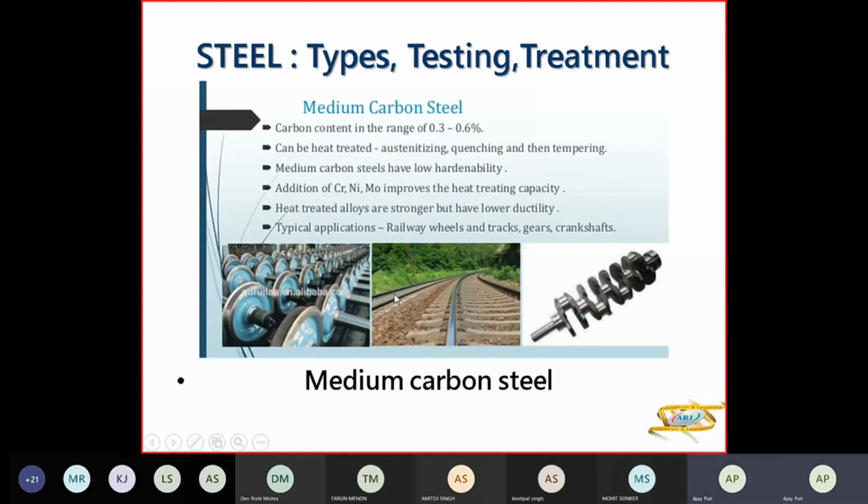this is HMS1. If you sell it as scrap, this is HMS1, which is malleable. So it can just be melting scrap, which can be melted in the furnace. Your mild steel cannot be directly melted in furnaces because it has mixtures. Here, this doesn't have mixtures. It can be made into reusable scrap where you can just melt it in the furnace and make another steel part. This is your crankshaft. These are the wheels of your train, which are also made of medium carbon steel.